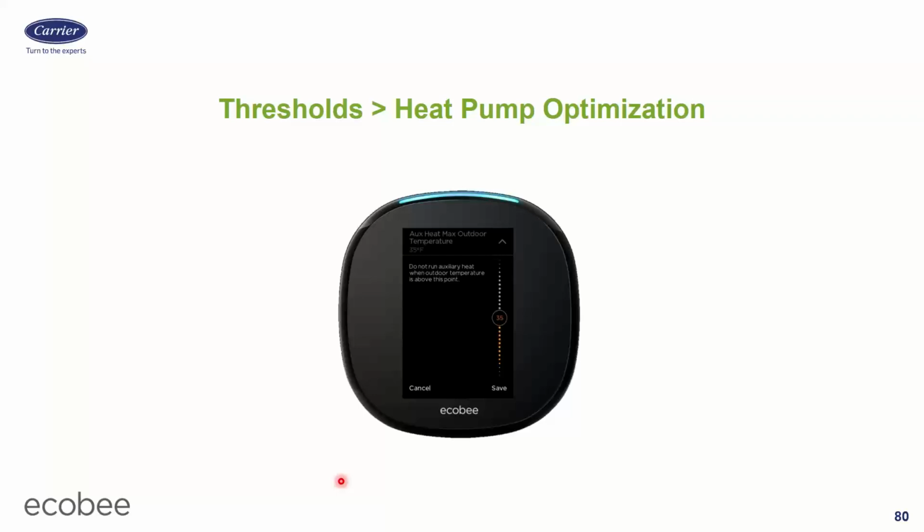So I'm going to need to pick some scenario in which I don't really need to run the auxiliary heat anymore. So right now on the slide, they're showing 35 degrees. So that means if it's above 35 degrees, I'm expecting my heat pump to do it all on its own. If it's below 35, I'm expecting the heat pump and the auxiliary to work together as a team. Okay? So I want to get this set for an appropriate amount.